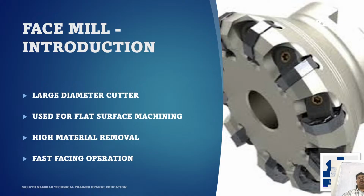Suppose a raw block has a rough saw cut on the top surface. You need a clean, accurate top face. Instead of using a small end mill and taking many passes, a face mill can cover a wide area rapidly. That saves time, improves productivity, and creates a professional flat surface. Face mills are common on VMC machines, especially for preparing stock before further machining. They are often one of the first tools used in a job setup. Raw material comes in rough, the face mill comes in, and makes it civilized.